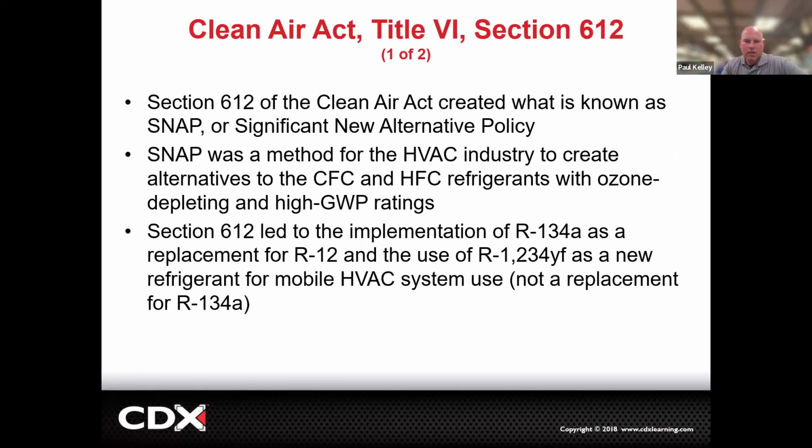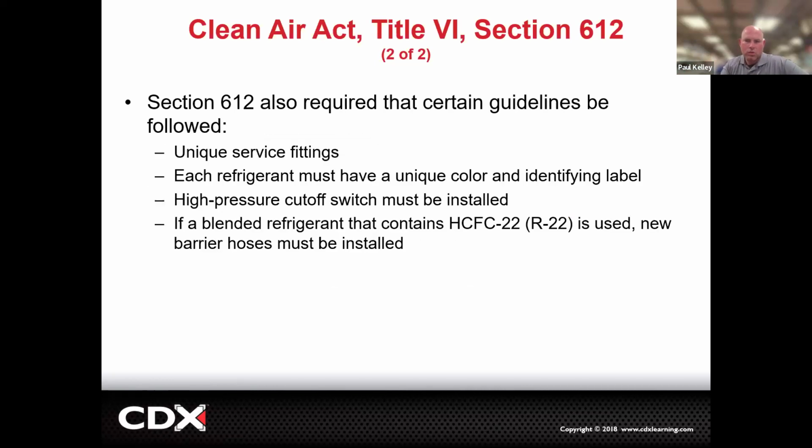Cool. So there are some other details. They have a lot of sections of the Clean Air Act stating what we do and why we do it. The reason we do the things we do is because it's law. Makes sense. It's a federal initiative. Cool. So Section 612 required unique service fittings. For example, if you try to hook up your R134A machine to an R1234yf system, it's just not going to work. You don't really have to study that sticker because the fittings are unique to YF, the fittings are unique to R134A, the fittings are unique to R12. Kind of makes sense. So it's not that crazy, but they do have labels.